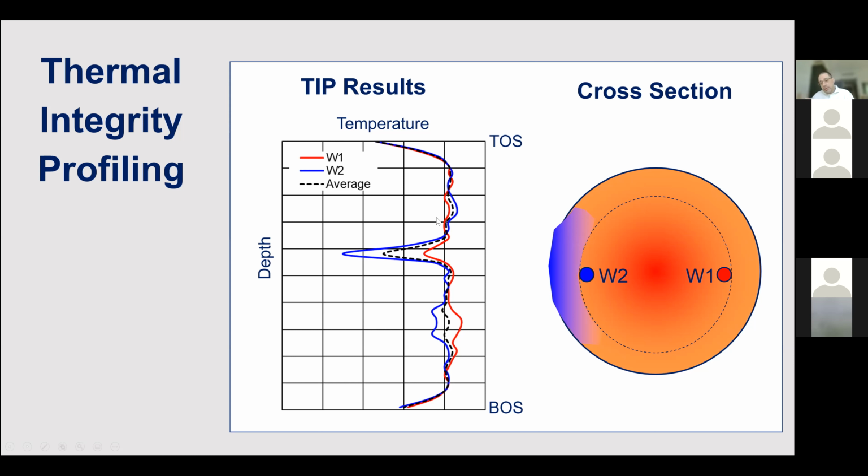Conversely, if you have a bulge, or a larger concrete volume, it will emit more heat, and that signature is going to be reversed, on the other side. So this immediately allows you to see that there's a defect, and it shows you that there's a cage shifting.